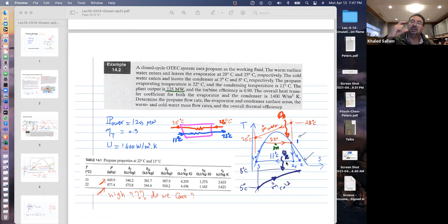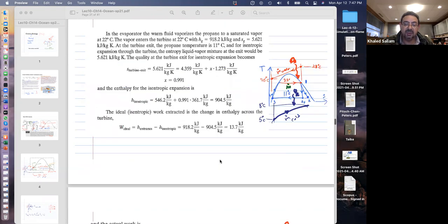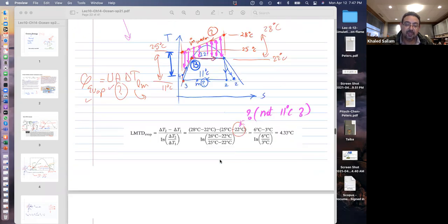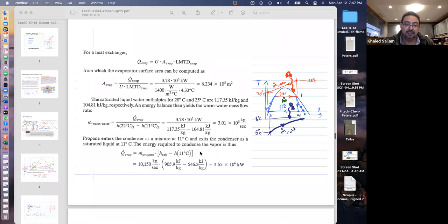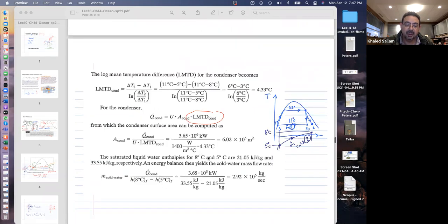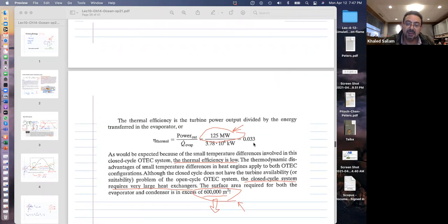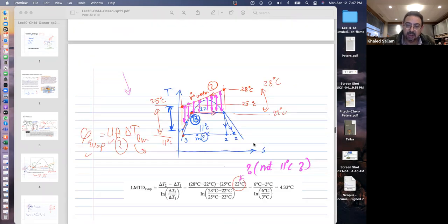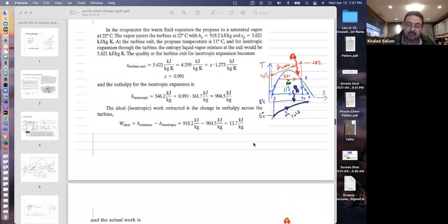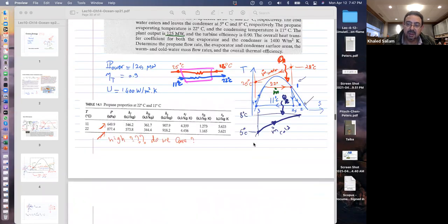So big delta T? No, very small delta T. Just 11-degree difference. So I mean, if we go and look at the efficiency, you'll find out it's not really going to be that big, right? Because of the small delta T, right? Let's jump and see the efficiency together. How much? 3%. Right? Surprised? No, I'm not surprised. I mean, what can you do with an 11-degree difference? You do 3%. That's what you can do, right?